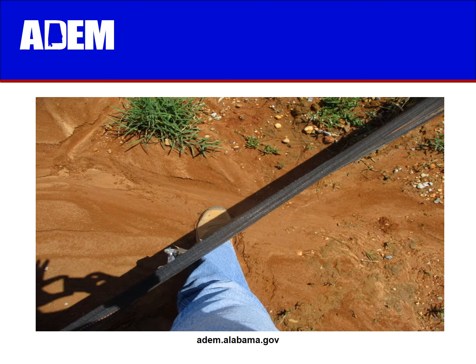One of the most common BMP issues is the improper installation of silt fences by not having the silt fence trenched into the ground. This allows soil and turbid water to run underneath the silt fence, rendering it ineffective.